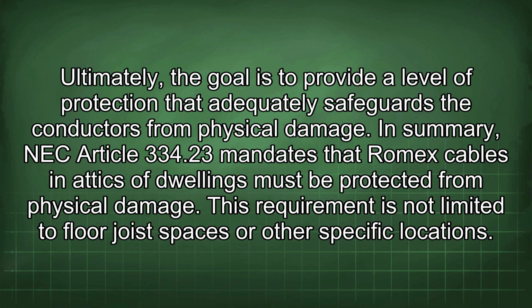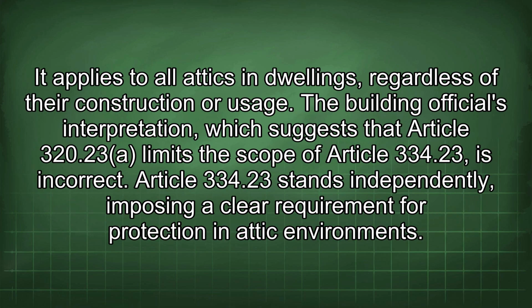In summary, NEC Article 334.23 mandates that Romex cables in attics of dwellings must be protected from physical damage. This requirement is not limited to floor joist spaces or other specific locations. It applies to all attics in dwellings regardless of their construction or usage.